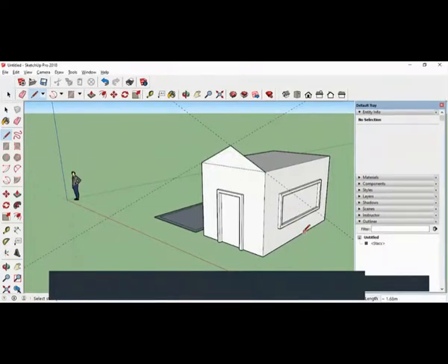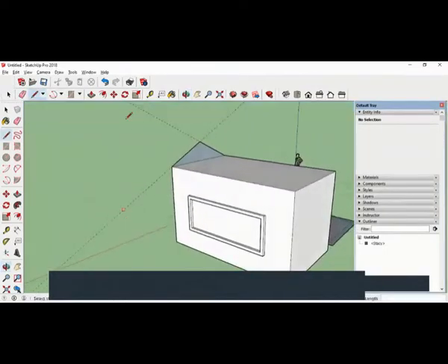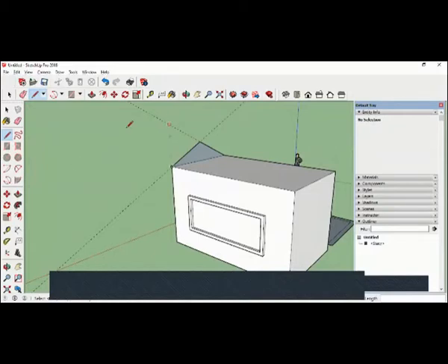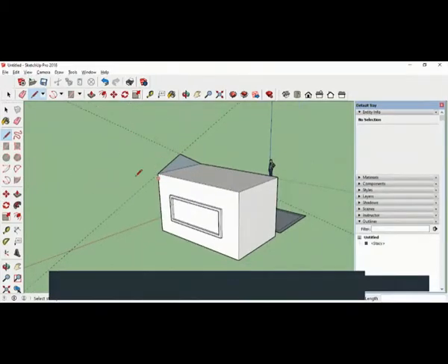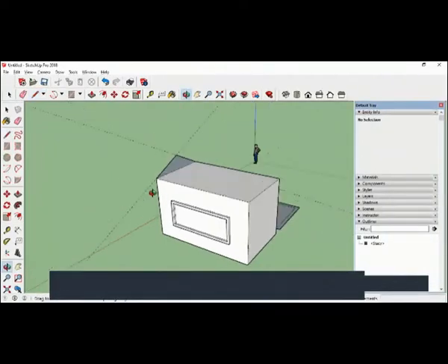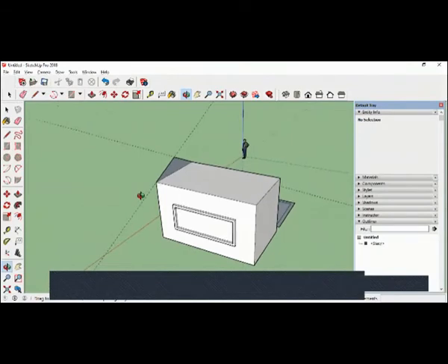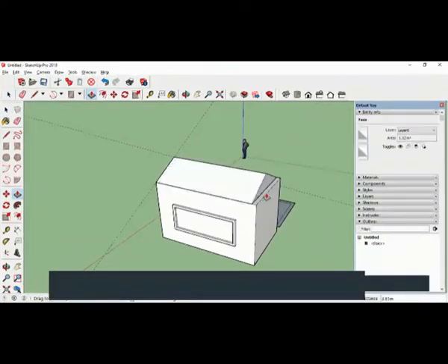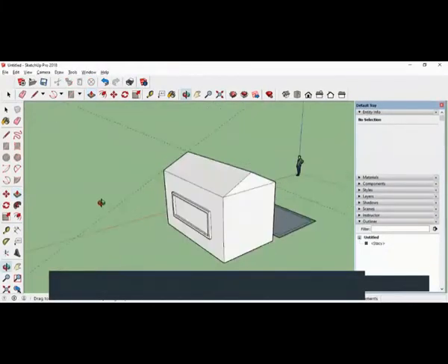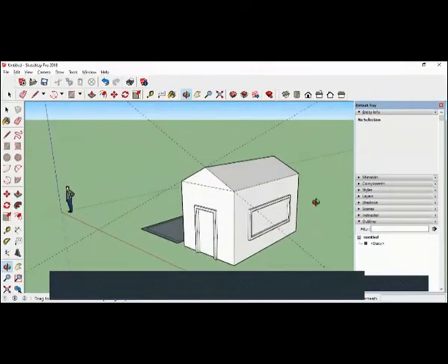Now let me use the center button and rotate it, or you can use the orbit to rotate. So I have rotated like this using the orbit button. I will use the push pull P, go here, drag it here. You see that one small green round that shows that you are with that end of that face. Click. You created a slope. See, you created a slope roof.